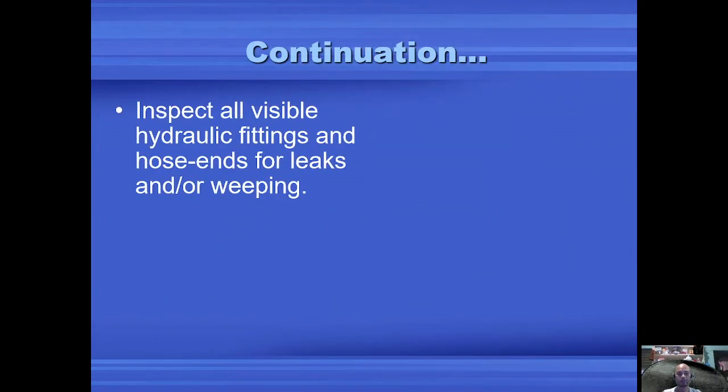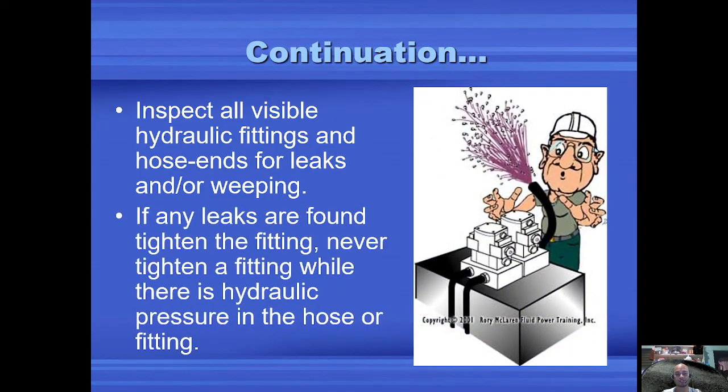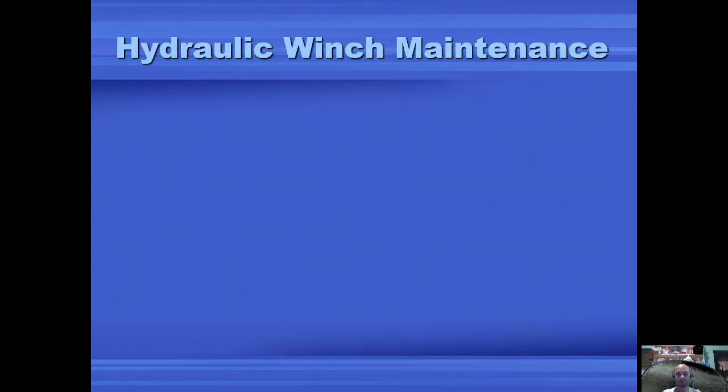Inspect all visible hydraulic fittings and hose ends for leaks and weeping. If any leaks are found, tighten the fitting. Never tighten a fitting while there is hydraulic pressure in the hose or fitting. Always tighten after stopping the system. Relieve the pressure first before doing any maintenance.